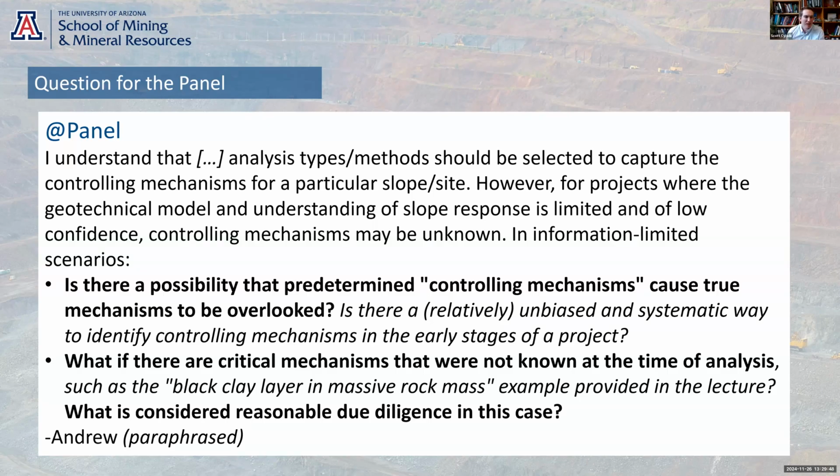Yeah, I think Mark hit the nail on the head with the comment on the geology there. Just because at the early stages of a project, usually we don't have geotechnical domains quite yet because we may not have enough data. So what we would normally do is use the geologic domains, so the geology domains, collect some structural data for a hard rock mine anyways. And the unbiased and systematic way that we look at it is just plot the stereonets, right? Plot the stereonet for each geologic domain. Then you can go through that, review it with your pit design, and get the first initial look at what the controlling mechanisms might be. So I agree with that.